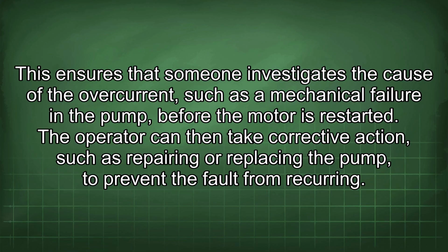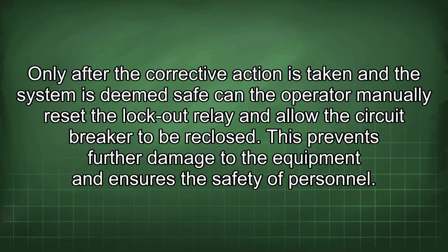fault from recurring. Only after the corrective action is taken and the system is deemed safe can the operator manually reset the lockout relay and allow the circuit breaker to be reclosed. This prevents further damage to the equipment and ensures the safety of personnel.